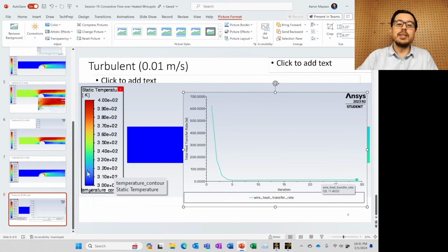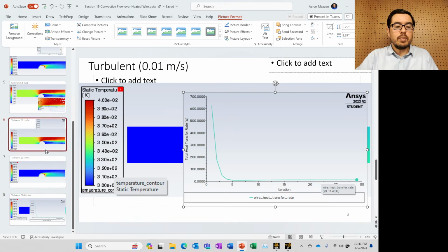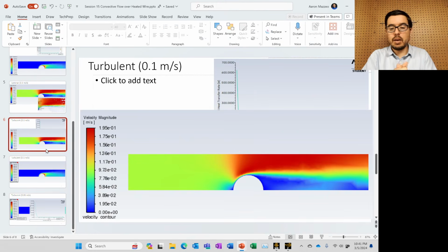So that's pretty neat, okay? That we can run this kind of calculation. And now we're talking truly coupled physics, where instead of having to use some type of correlation or some type of h, we're able to run our air, run our boundary condition for that temperature, and we can figure out the heat transfer coefficient.